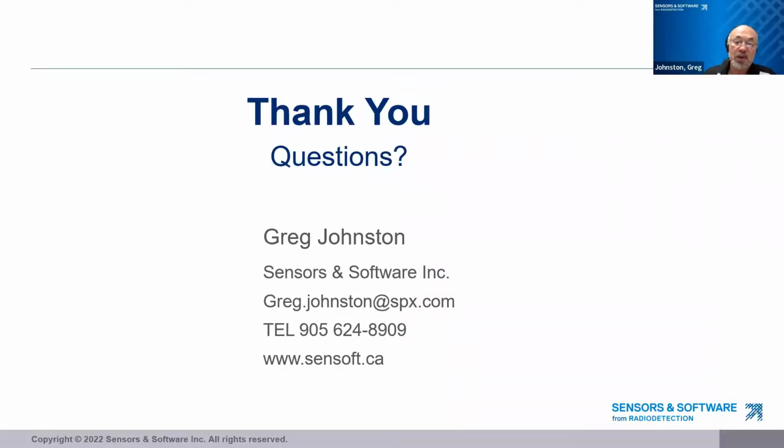Will the data processing part be available in the future? Well, one of the things that you can do with SPIDAR SDK is collect the GPR data and save it however you want. One of your options is to save it in the Sensors & Software data file format, which are DT1 files and HD files. Some of you will be familiar with those. If you save it in that format, then you can use our EKKO Project software to visualize and process the data the way you want. Okay, so that's an option.